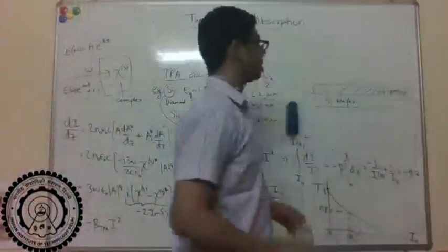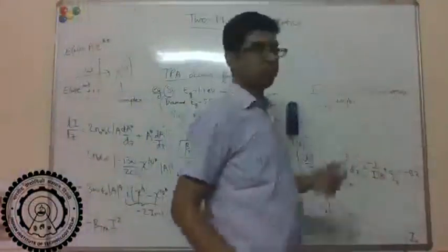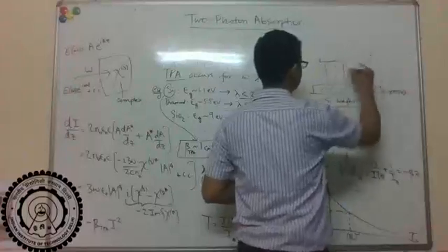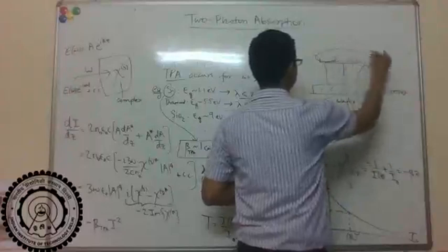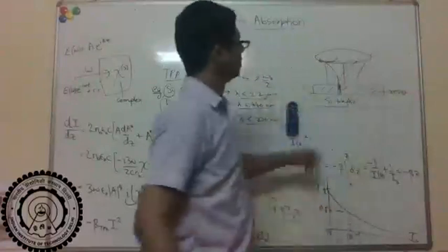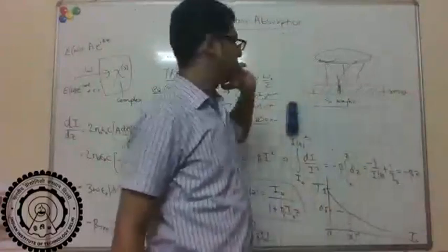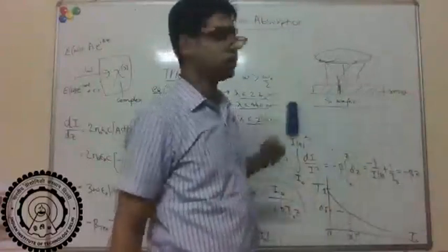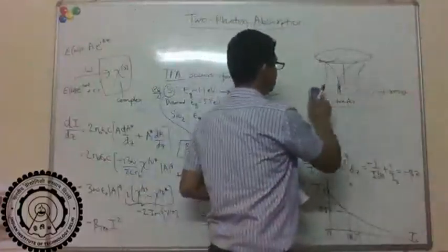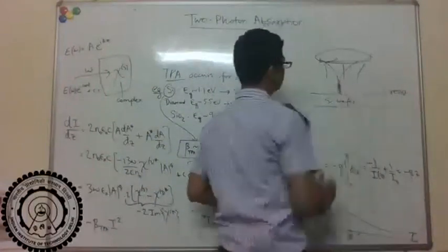So there is a material called photoresist, which you coat onto this wafer, right? And then you illuminate using some pattern. Again, let's say you can imagine there's a lens here, and I'm focusing light and illuminating a very small region. And wherever we expose this resist to the light, it changes its chemical properties, for example, dissolvability in some solvent, right? And so when you expose this and then you dissolve it in the solvent, basically the unexposed part goes away, and only the exposed part remains.